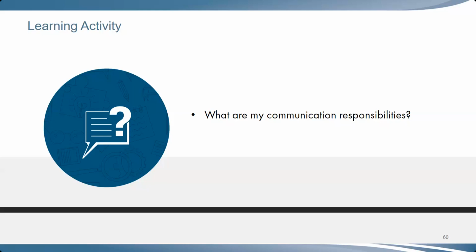Yeah, correct. So whenever you're doing unit testing in real time, just put a unit test card in OMS, put the availability on it, and what your scope is. But say you're getting a dispatch right now till noon at 50 megawatts, and you have to shut down at noon, and there's something we want to test on the unit. If you want to deviate for 15 more minutes and test that resource for an additional 15, please reach out to us and let us know the circumstance, and hopefully that makes sense.